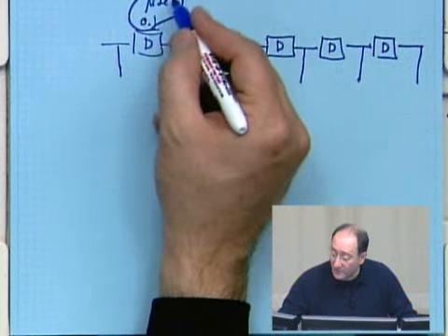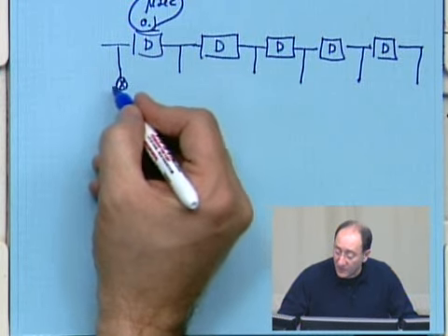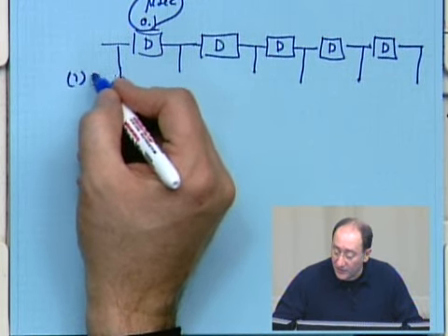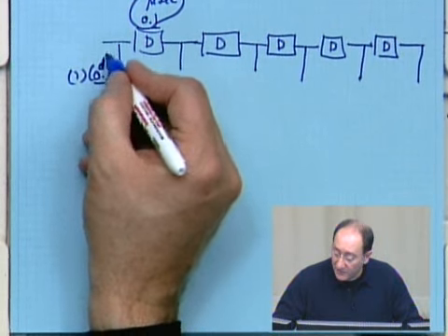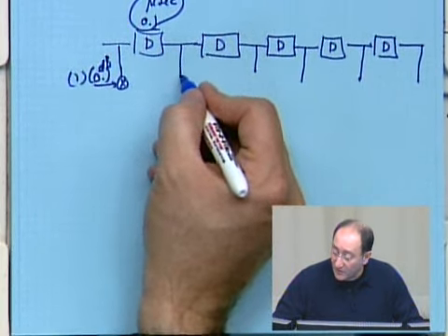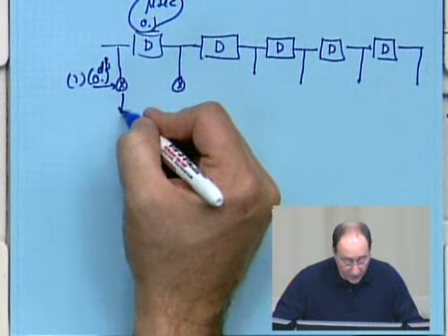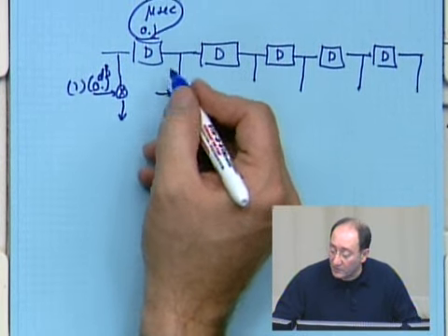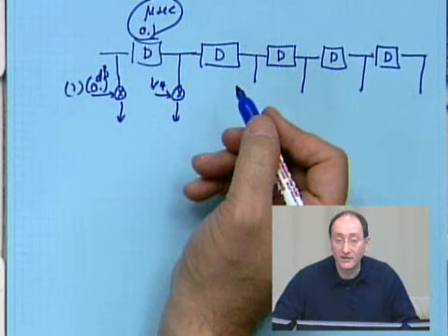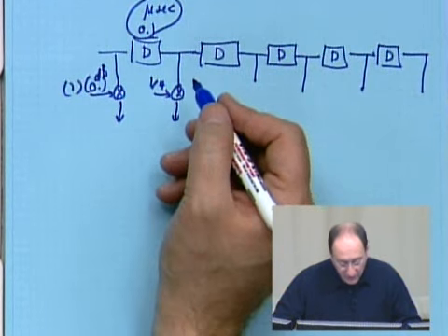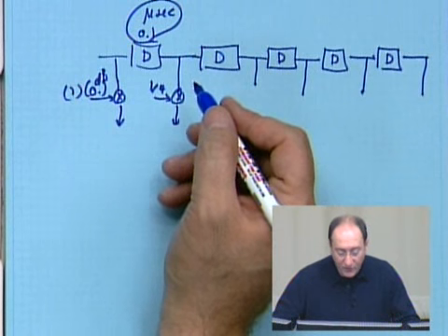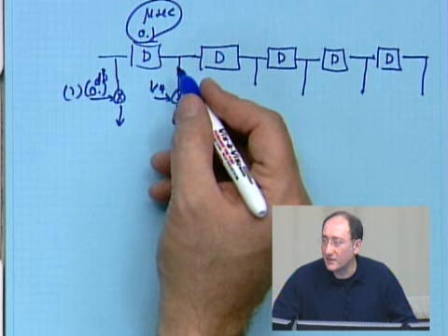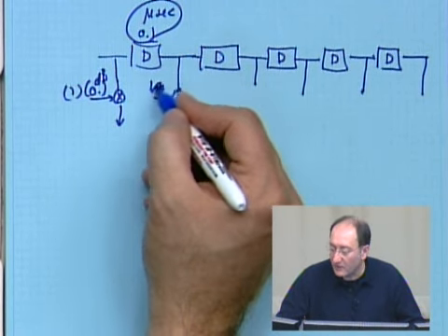Each of these taps is how much? 0.1 microsecond. And then the first one is multiplied by the equivalent of 0 dB, which is 1. Okay? 1, which is 0 dB or dBm, whatever. The second one is 4 dB below that. 4 dB below that is like 1/4? No, 4 dB is not 1/4. I have to calculate it, because 3 dB is 2 times. 4 is something like, I believe, 2.5 times. I don't know. You have to just calculate it.